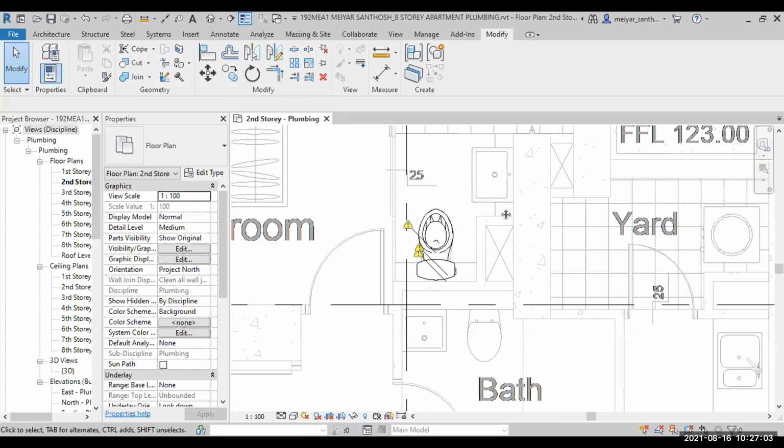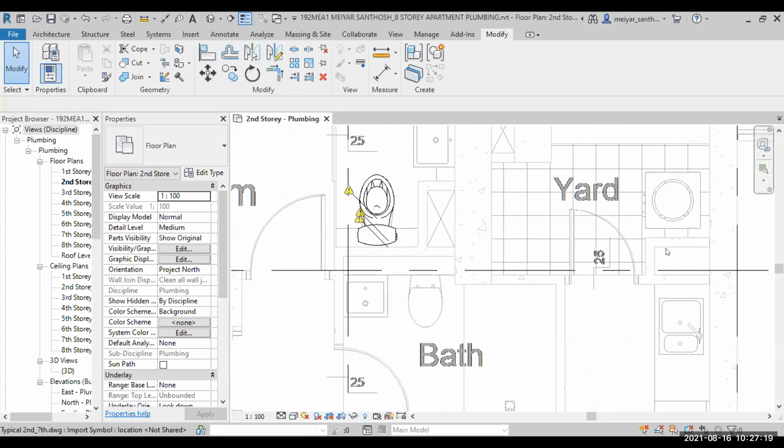Okay, I think more or less it is there already. Right? And then this one, if I want to connect the sink and washing machine, I can put the sanitary pipe here, right? The washing machine and then the sink, this one also needs to connect to the sanitary pipe. Of course, because this opening is meant for your sanitary pipe, for your waste water. Then the washing machine water could drain to here also. There should be a pipe there.